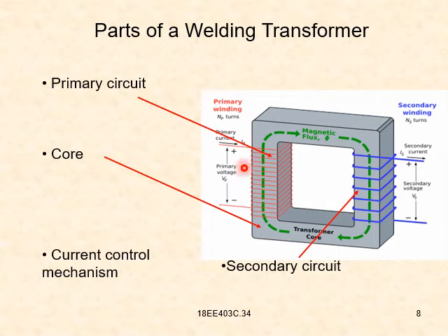That means more voltage and less current in the primary, and less voltage and high current in the secondary. Whatever the number of turns, there is no change in power from primary to secondary. Voltage and currents may differ, but there is no change in power or frequency.